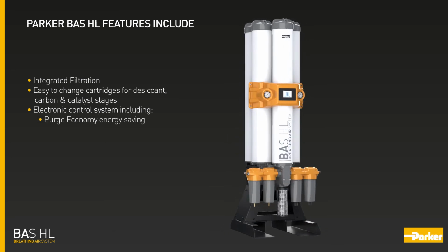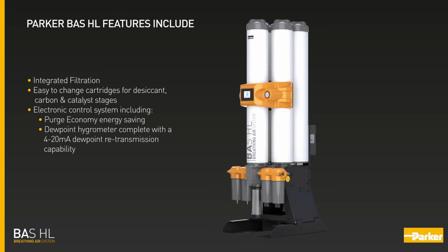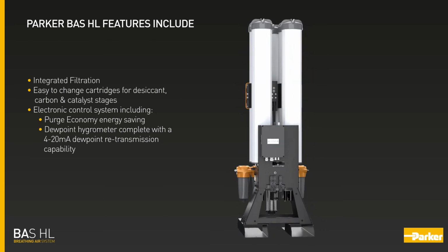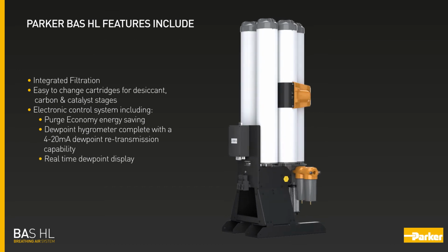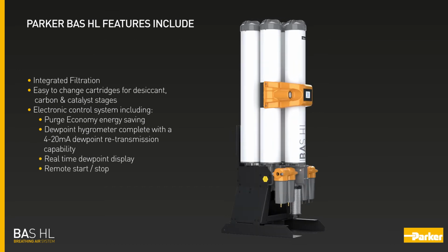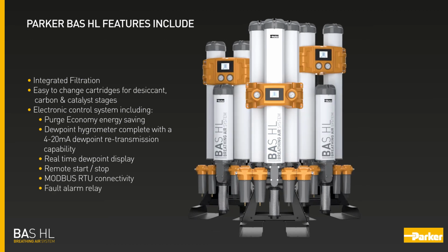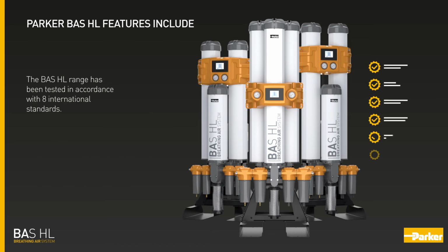purge economy energy saving, dew point hygrometer, complete with a 4 to 20 mA dew point retransmission capability, real-time dew point display, remote start-stop, Modbus RTU connectivity, fault alarm relay. The BAS HL range has been tested in accordance with 8 international standards.